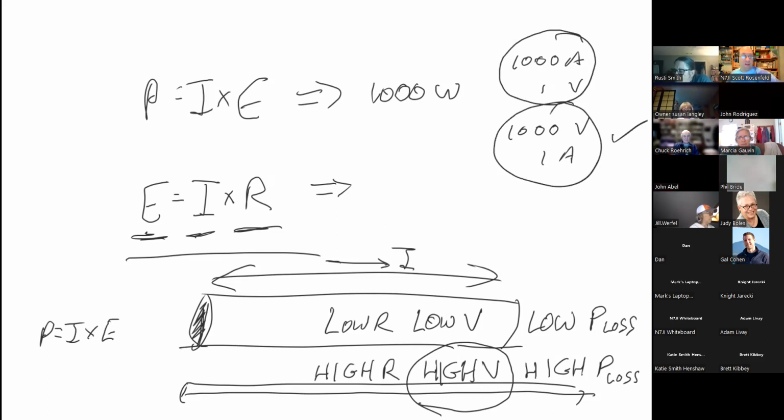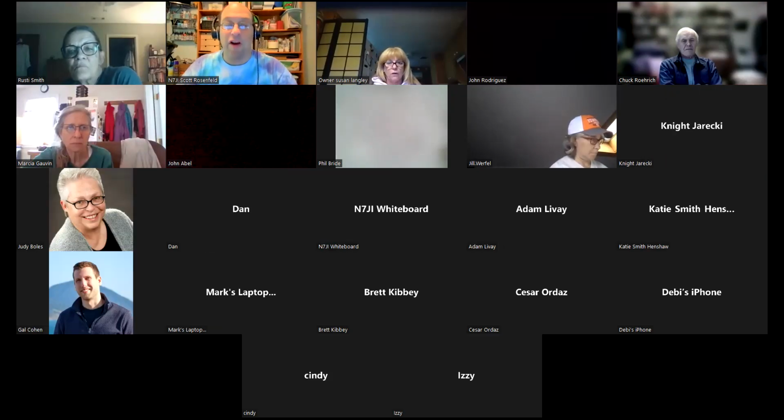And that's why if you get a toaster, for instance, or let's say you have an air fryer like we love at our house, that air fryer has heating elements. The heating elements operate at high voltage, but it also has a touch panel, which is basically a computer. So internally there is a power supply that generates a control voltage to run the touch panel, a very low DC voltage, but there's still the external voltage coming in that's then used to turn on the heaters. So there's a power supply in there, you just don't see it.